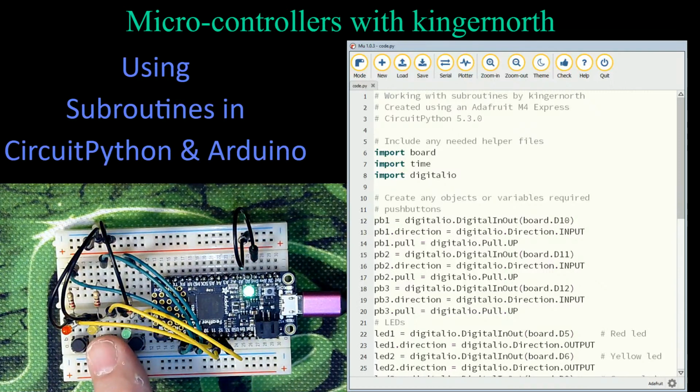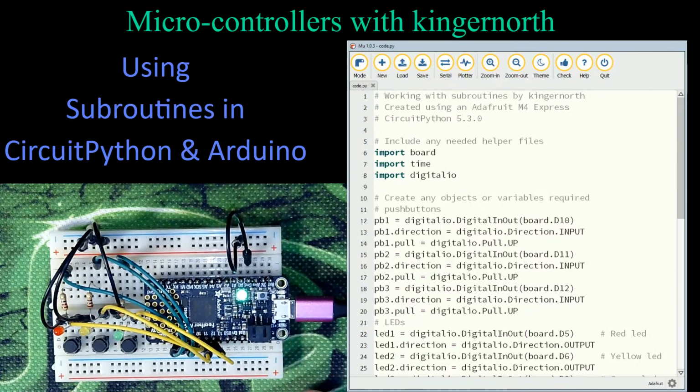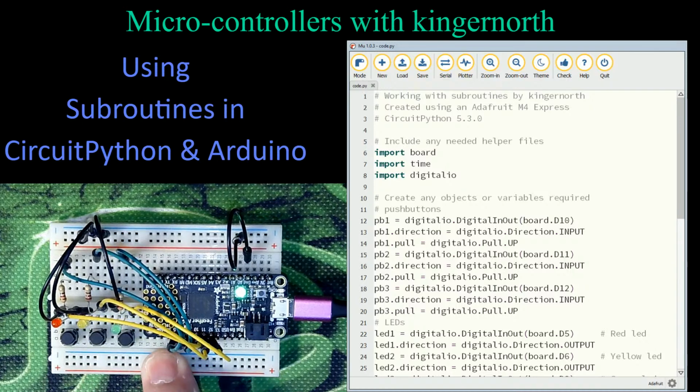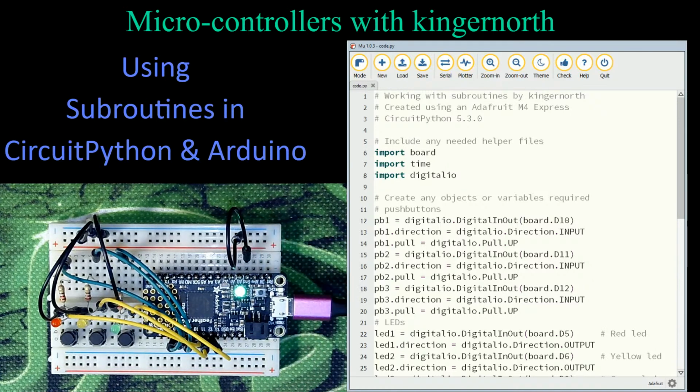And I also put in 3 resistors, and those are 220 ohm resistors in this case because this is a lower voltage. Even though this is 5 volts coming in on the USB, this board works on 3.3 volts primarily. And I am connected to the 3 volt lead on this side. So that's normally my normal voltage. That's what my pins are going to output by default. So that's the reference. So let's have a look at how I built up this program.